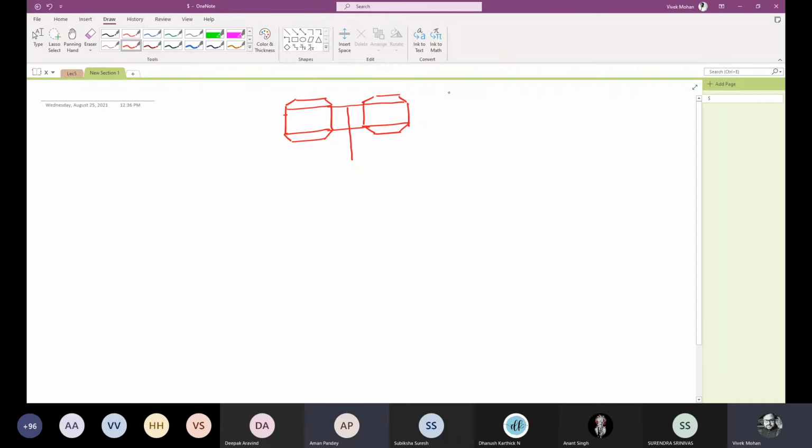See, if I am connecting three such cells like this, VOC for one solar cell will be 0.6 volt. Now I have connected three solar cells, each having a VOC of 0.6 volt.